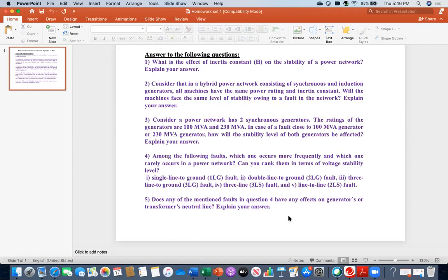And also, what happens in real practice for the telecommunication line, the telephone line, is that typically they share the common neutral line. They share the same neutral line of the generator or transformer or the power. So it might happen that those zero sequence currents start flowing through that line, and that may interfere with the telephone communication. For example, when you are talking over long distances, you face some interference. That could be the cause, that some current is flowing through the neutral line. So those are the effects.